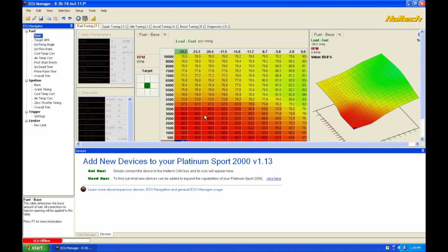So before we do any transient throttle enhancement tuning, we want to make sure that our main fuel table here is tuned as accurately as possible. Now, you're going to run into this situation again. If you blip the throttle, it's going to have a lean stumble. What we're interested in to build this table up is having gradual throttle movements so that we can characterize the amount of actual air mass coming into the engine under normal throttle movement, compared to having that large change, or that delta throttle change, as we hit the throttle and try to increase our load or our RPM very quickly.